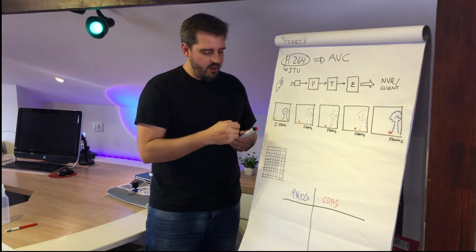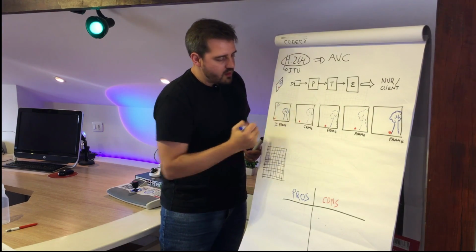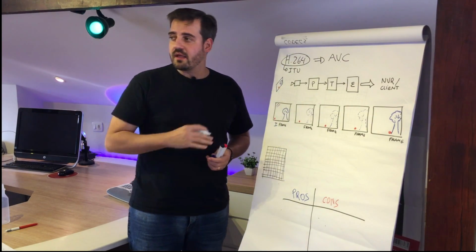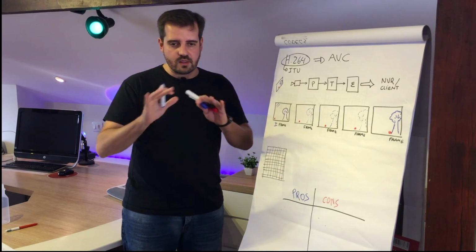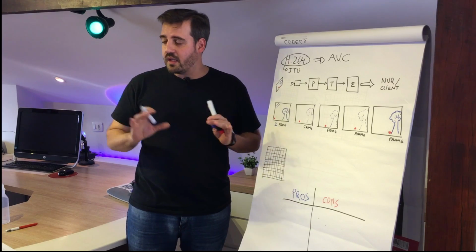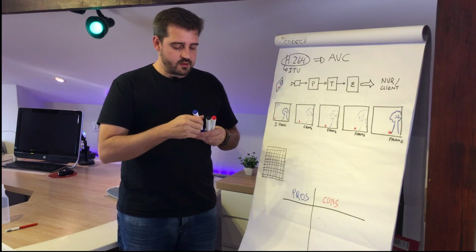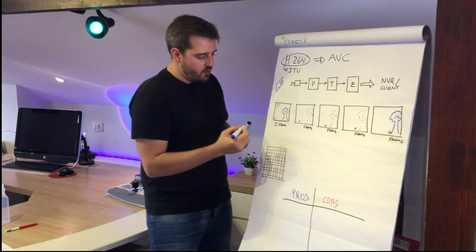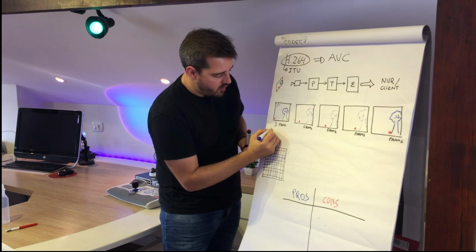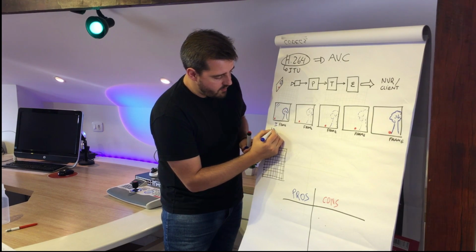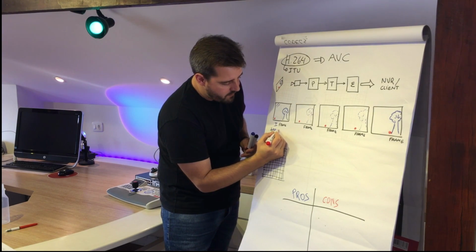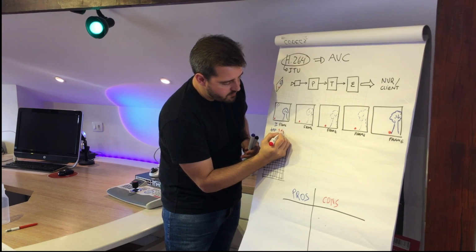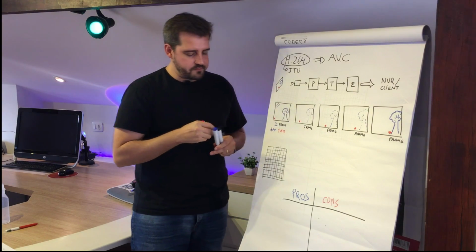This frame will actually be the complete frame, just like the MJPEG. The complete frame with all the content, all the image as it is, without any calculation. This means that we have a low processing power, but we'll have a high bitrate for this I-frame.